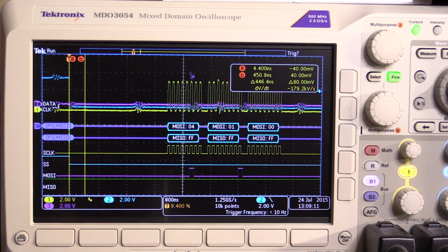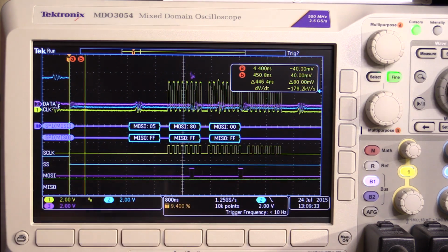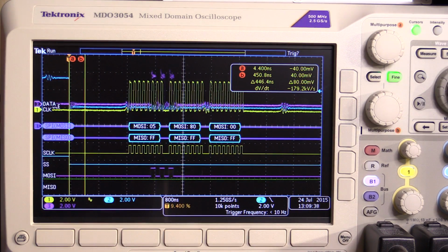Let me flip to one of the other channels for a moment, and we'll output to DAC 1. If I output, let's say, 32768 on that one, that should now be writing to register 5, which would be the first byte, and you should see the value I'm outputting on these two. There we go. So now, as you can see, it's 5 and then 8000, because I've outputted 32768, which is the 16th bit, or 15th if you start from 0, being set on the data. And if I output 65535, then you'll see it being FF.